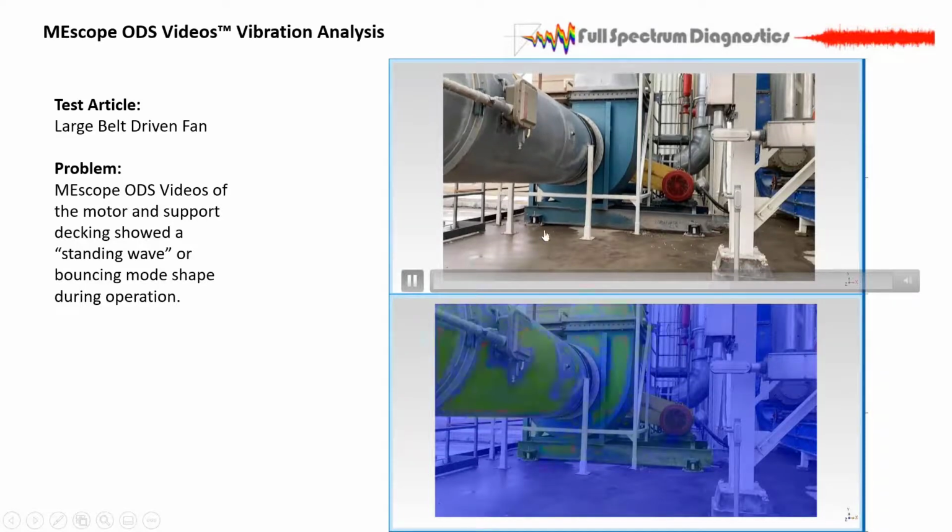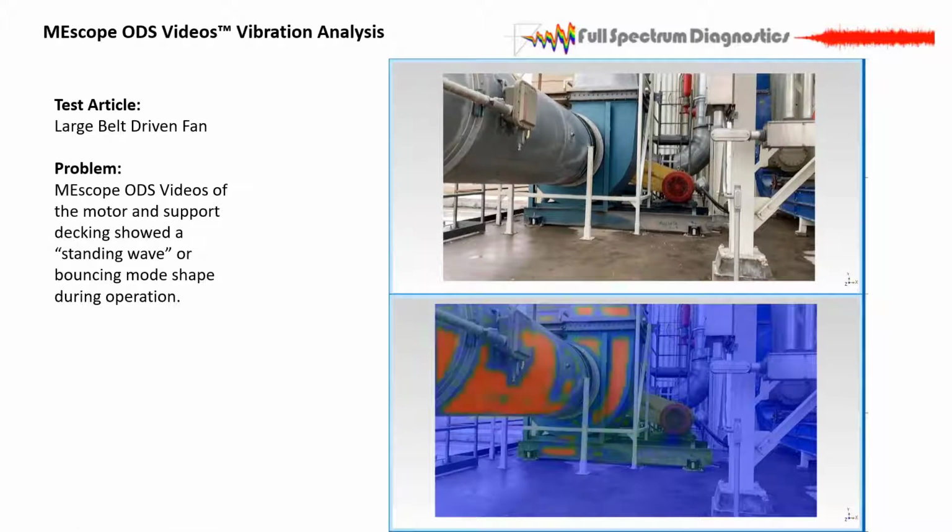They tried to use the same holes that the other bottomed out isolators were in, and it caused some problems. They were a different size isolator, and so they left the old ones in on the back side. So you have something that has 4 isolators that probably needs 6 to do all the work, and only 2 of them are actually reacting the way they should. So the vibration in the area was up pretty high.